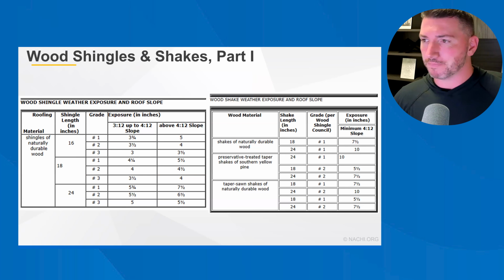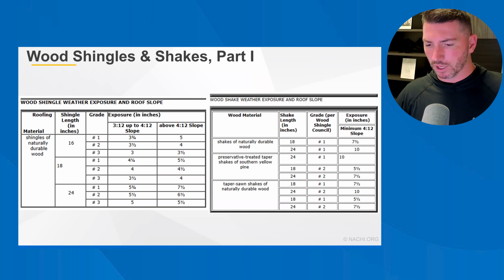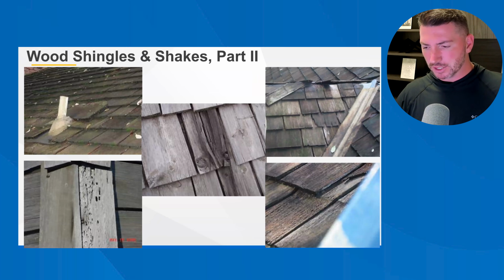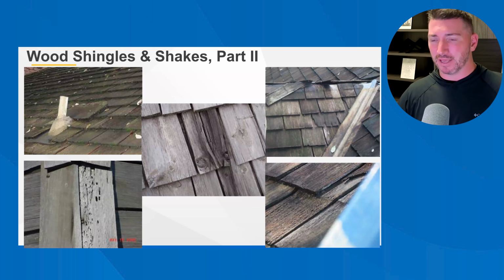unless Noah built them. Wood shingles and shakes. We'll talk about them really quickly. We'll just kind of breeze through. Shingles and shakes should not be used interchangeably. Shingles are manufactured and saw cut on both sides. Traditional shakes were hand split. They're not usually hand split anymore. They're usually machine split, and they usually have a machine cut on one side with an irregular shape on the other side, just to kind of maintain that storybook look that people really enjoy.